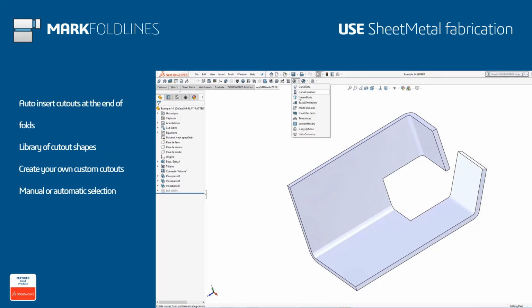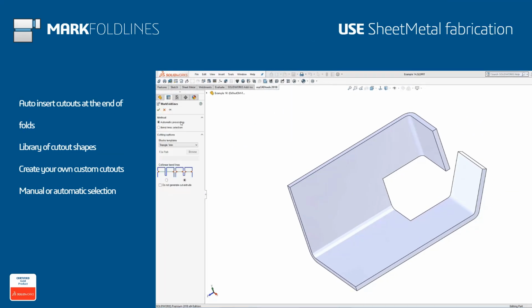MARKFOLDLINES. MARKFOLDLINES enables you to automatically create cutouts at the end of each fold line for each sheet metal body. This can be done from part level or on multiple sheet metal parts at assembly level.